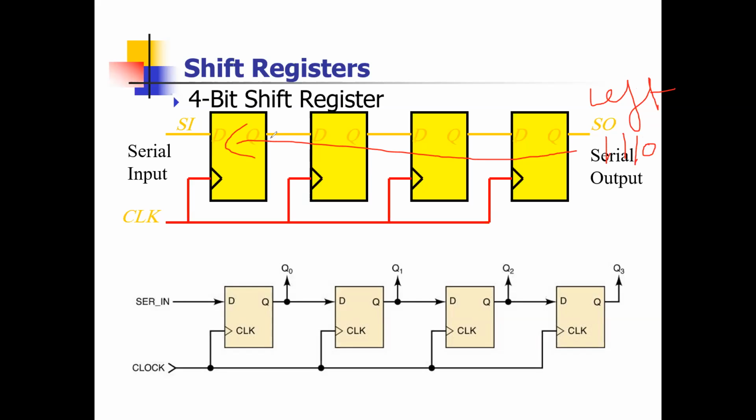Clear? Yes. And a very important thing you can see here is that all flip-flops are connected together with the clock. Yes, with one clock. Because we want all flip-flops to give the result at the same time. As I told you before, even for a register, we are using several flip-flops at the same time. So it will be very difficult, and the result will not be synchronized and there will be delay also if I give an individual command to each flip-flop. So that is very important for the register, that we need to give the same clock here. Clear? Yes.